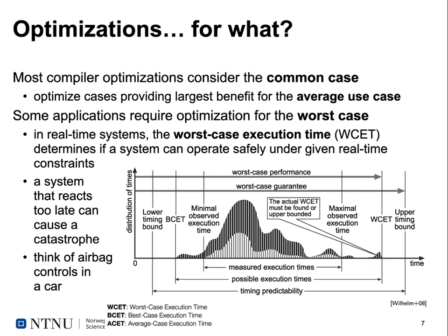So if you decide your system to be only as fast to ensure that the largest measured execution time for whatever 1000 experiments would be able to adhere to, but not the worst case execution time that might really occur, even though it's some strange combination of parameters maybe that leads to this, then your application is unsafe to use.